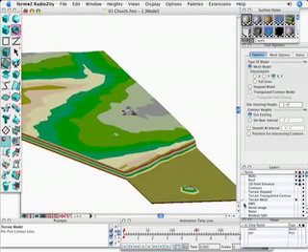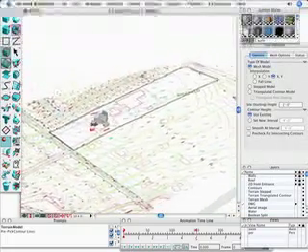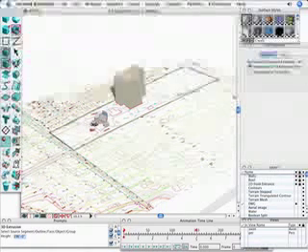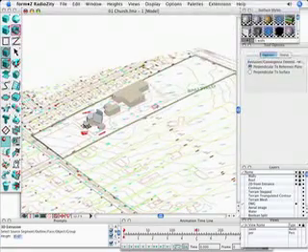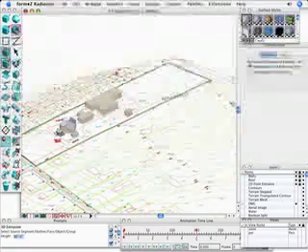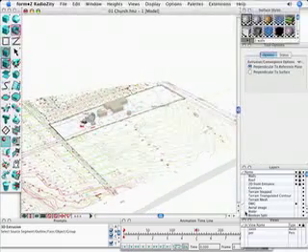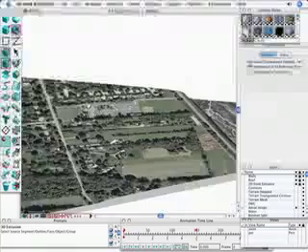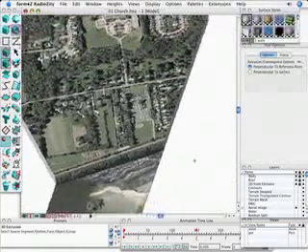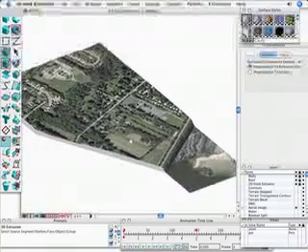We can map a series of surface style textures, such as a color gradient scale, to represent elevational heights. We can import drawing files and map those onto the 3D solid terrain. When we import those files, as we saw earlier, you can also take that imported data and extrude that into 3D geometry, besides mapping it onto the geometry that we have, as we show here. You can also import satellite or aerial photographs that are at a specific scale. You can map it right onto the accurate contour line data that we have there.